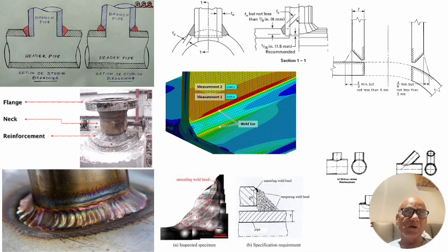So positioning of these weld beads, getting this throat, ensuring that there are no defects, undercuts, no stress points, fusion between the layers, fusion with the vertical wall, fusion with the horizontal wall, all are required to be seen and taken care of. And if it is a nozzle, and especially a nozzle which is at an angle, it becomes still more difficult, and a lot of practice and care has to be taken. I am sure with these inputs you will be able to look at fillets in a different way; what is normally considered very easy is no more easy.